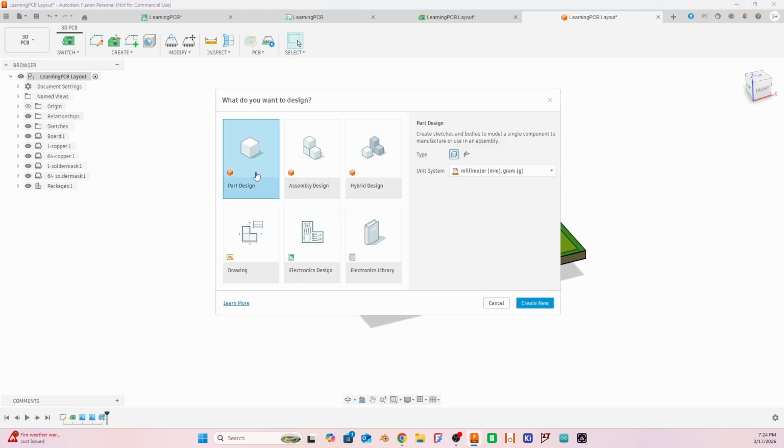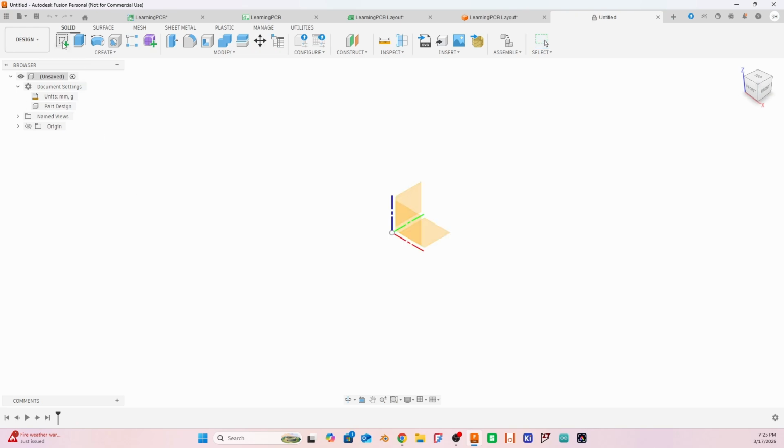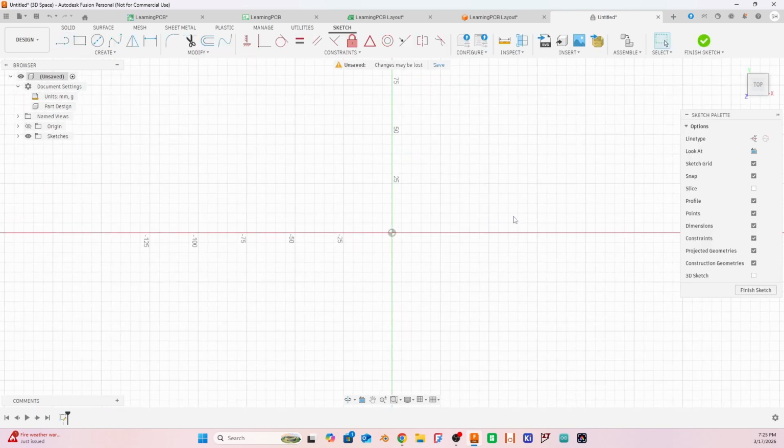So we want to create a new design and then go to board design, and I'll go for the sketch. So I'm gonna do something like a triangle. Let's see if I can find a triangle in here. No, maybe we draw it manually, it's fine. And we draw something like that. And then add some dimensions. Let's say this one will be 50, okay? And add a 50 here too. That's perfect. And this one too will be just 50, the same, okay?